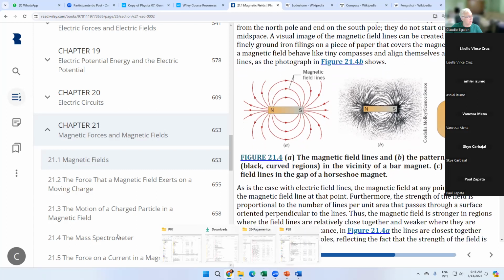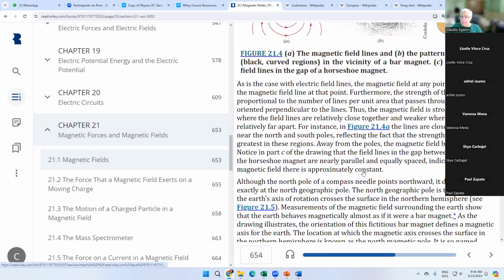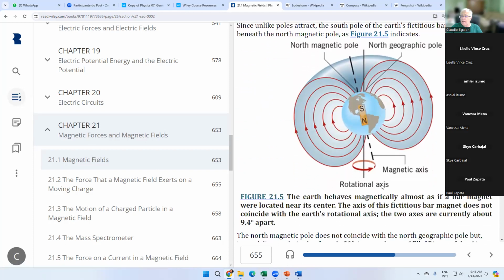Okay, and here you go, the Earth's magnetic field. See the polarity here inverted, north and south, right? If we are somewhere around here, let's say here in California, this angle here is the deviation of your magnetic north from the true north. This deviation in California is something around 10 degrees only.